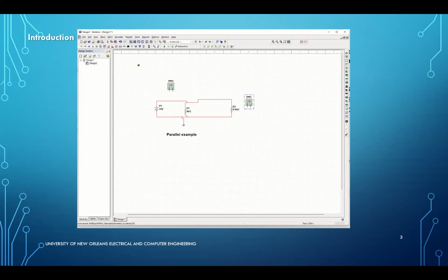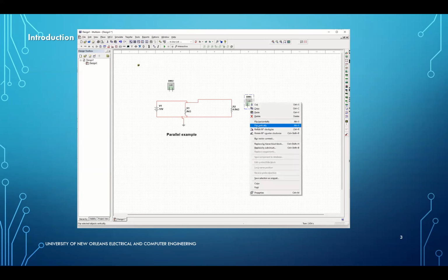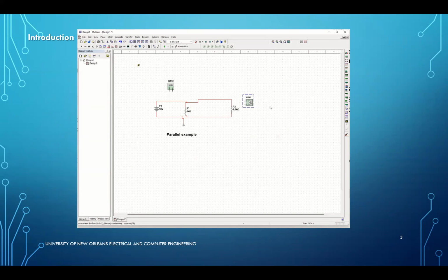By the way, if it's more convenient, you can rotate this. So now the connections are easier to make, although that's unnecessary, really. So I'm going to hit this one at the bottom of the resistance and this one with the top of the resistance. And that's going to measure my voltage. And on this one, remember, I'm going to have to break the circuit because I want to measure the current coming out of the source.